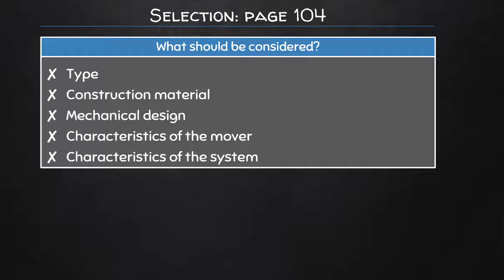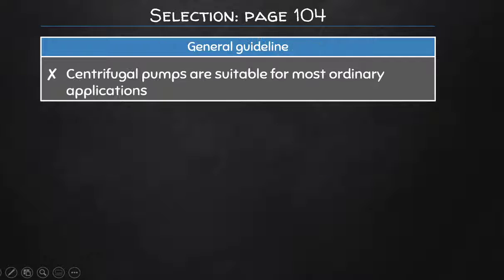How does the pump work? How does it operate? Are you going to have any electrical sparks that you need to protect against because you may be pumping a flammable liquid, for example? Now, once all of this is known, all these details are known, the characteristics for the fluid mover can be chosen to match the particular characteristics of the system that will be using it, of course.